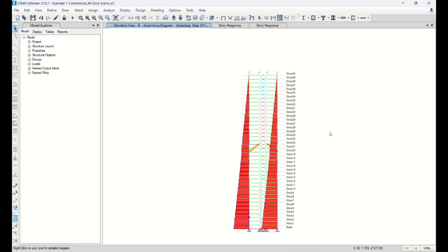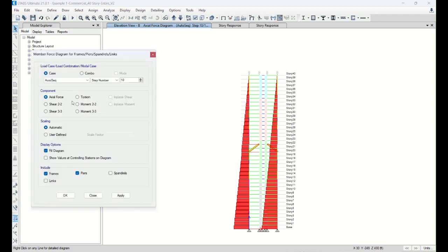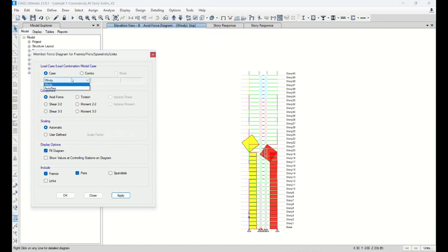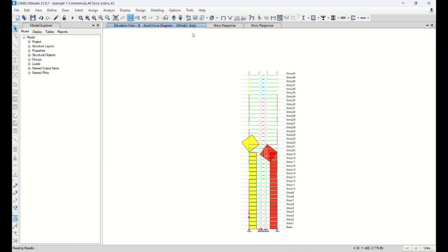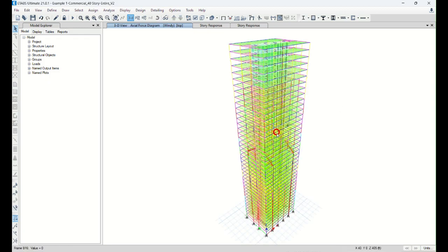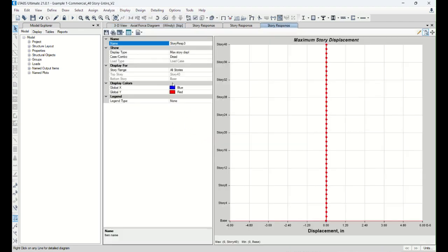So we can simulate this model and address the gravity load distribution and also lateral load distribution. Again, in this model, we can see the actual forces due to the wind. So see the compression and tensions. X direction is shown; usually you need to rotate to look at the other direction. So I'm going to put this one right there, 3D. So I want you to first update your model and also include your lateral deflection study, right?